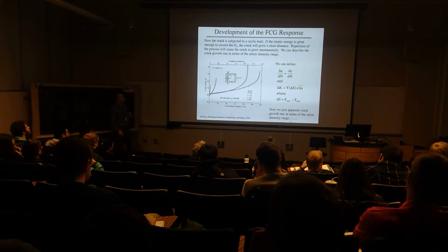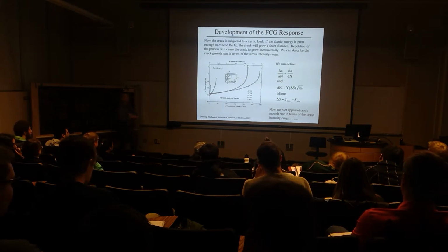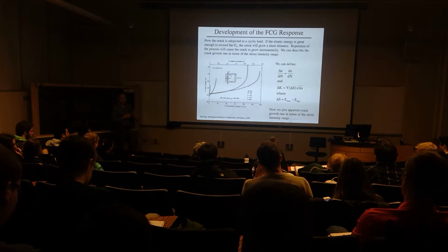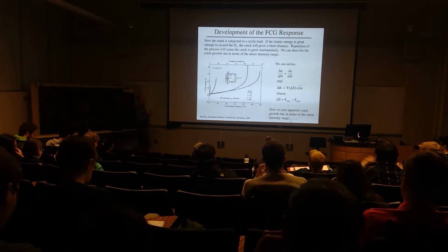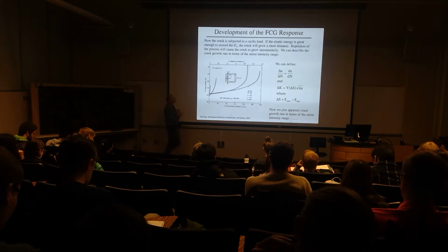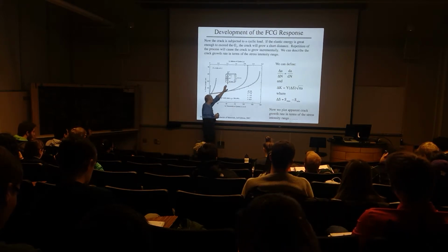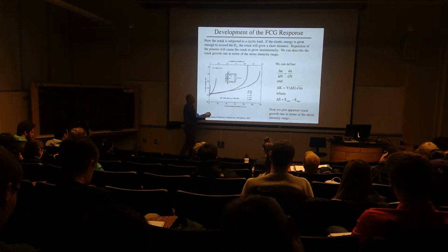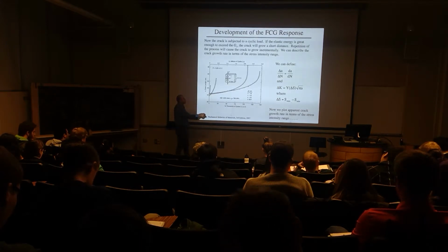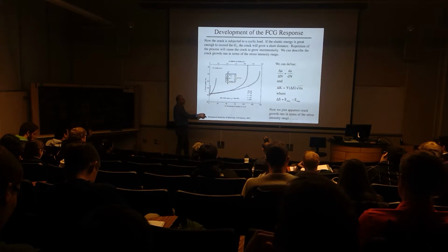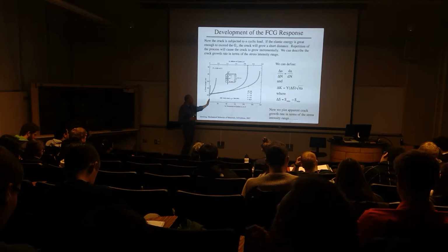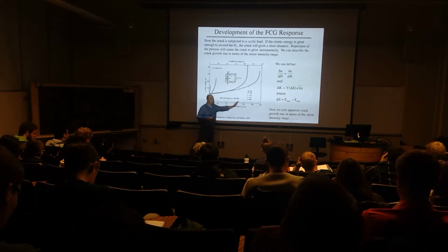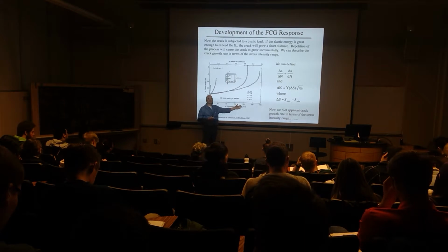And then what we're going to do is conduct cyclic loading to be able to monitor that incremental crack growth as a function of the cyclic loading that was applied. So we will plot something that probably looks just like this. We'll have our specimens, and we'll subject them to a cyclic load with a range of that cyclic load of a certain magnitude. And then we'll plot the crack length from an initiation point through the point where it goes unstable on a graph that looks just like this.